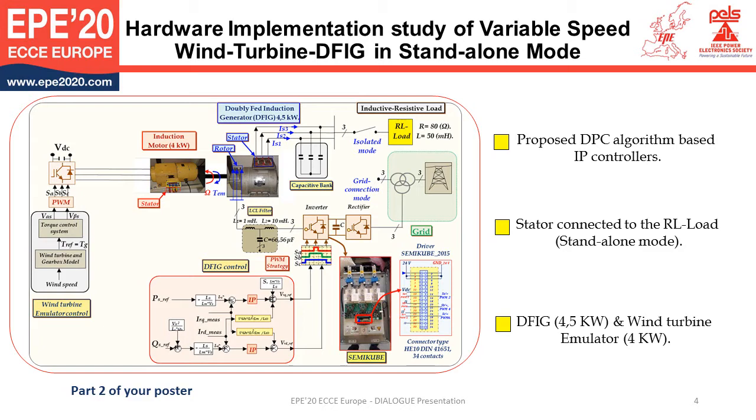We use the LCL filter between the rotor and the inverter, and I'm trying to explain why this choice in the future slide. So we will justify our choice. And we have the stator connected directly to the load with a capacitive bank. So for this reason we can say that we have the standalone mode.